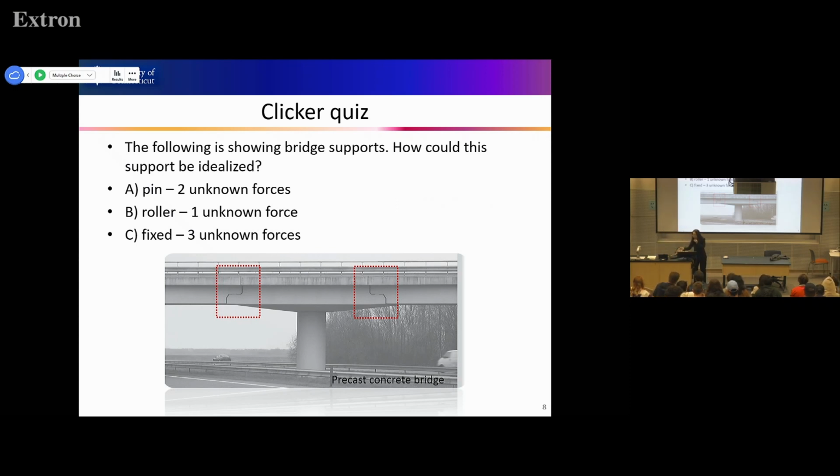So let's think about it, start with fixed. If it is fixed, then it cannot move and it cannot rotate, right? And then there is a gap, right? If there's a gap, then if there's a thermal expansion, then it can move a little bit, right? There's like a 2-inch gap, right? And there is concrete. Then concrete can expand and then shrink under thermal fluctuation, right? And because of this gap, this can move in translation in the x direction, right?